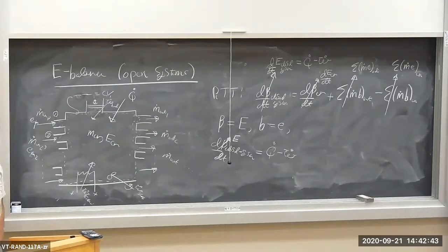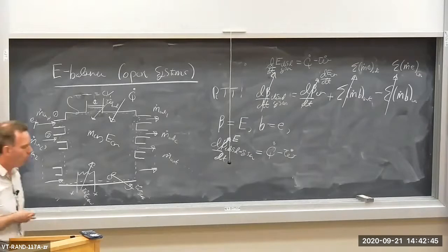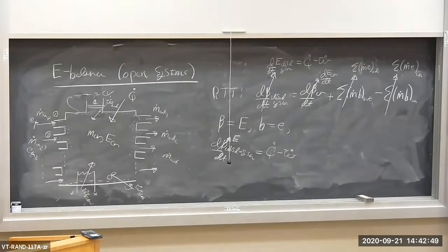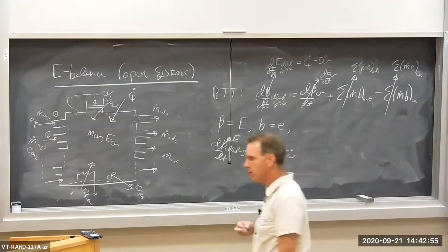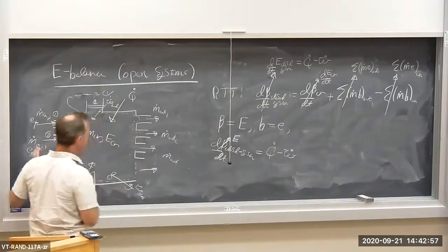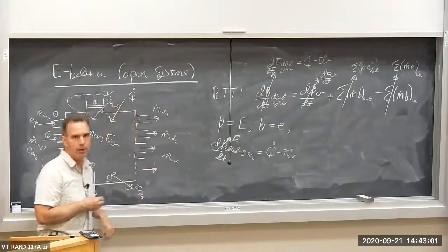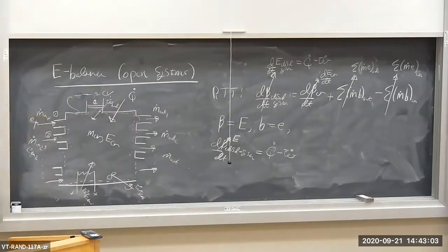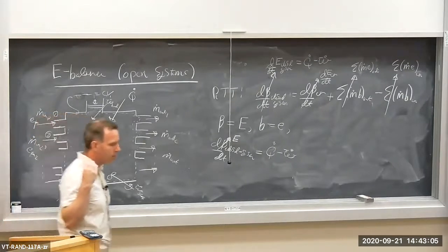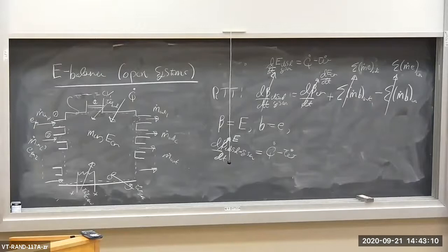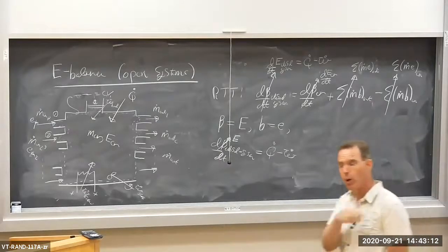There is a fourth form of work or power being done when we have an open system, and it's associated with pressure. We're going to call this pressure work. It's the work required basically to force the flow in and then force the flow out. Remember the previous three were boundary, shaft, and electric, but now we have a fourth, which is pressure work.